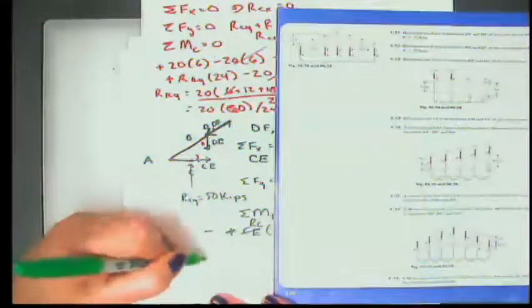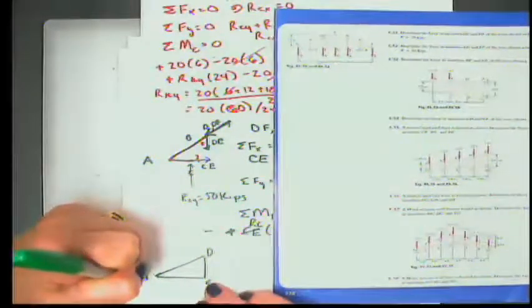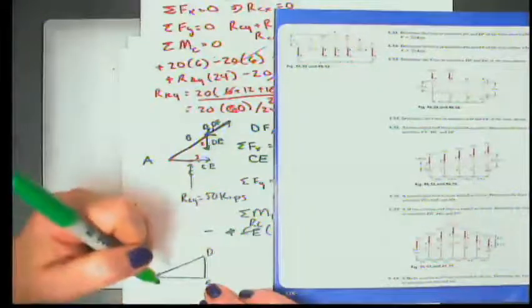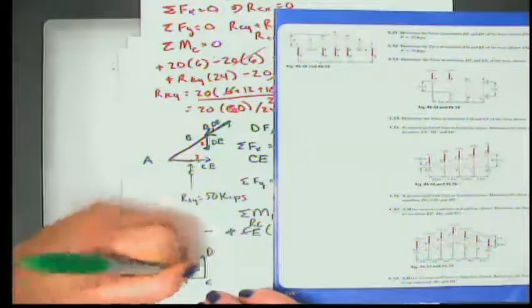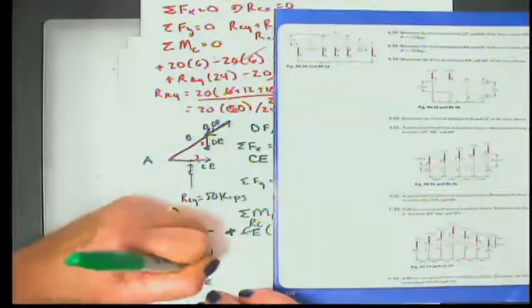So if we look at problem 651, from C to D, what is that vertical distance? Well, we're going to have to do a little bit of trig to find out what that is, don't we? So in other words, we need to know this length right here, DE. Okay, so if I do a little DE, it looks like this. A looks like this. This distance from A to E in the horizontal direction is 12 feet. And now we can find this angle and then solve for the distance DE.